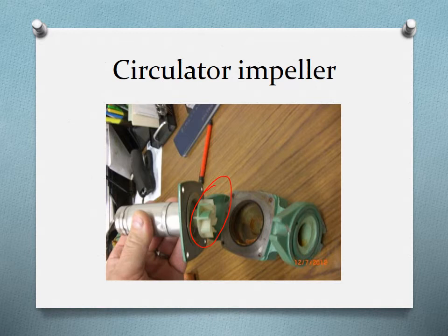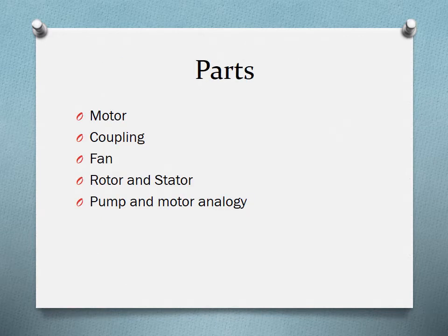It only pushes the liquid around, adding pressure, so it will be pushed around here, and eventually it will come out of this opening. So the impeller is completely designed differently than a pump. A circulator just thrashes the water around to give it more pressure. Meanwhile, the pump impeller has the ability to pull the water or liquid inside, even against vacuum or air.